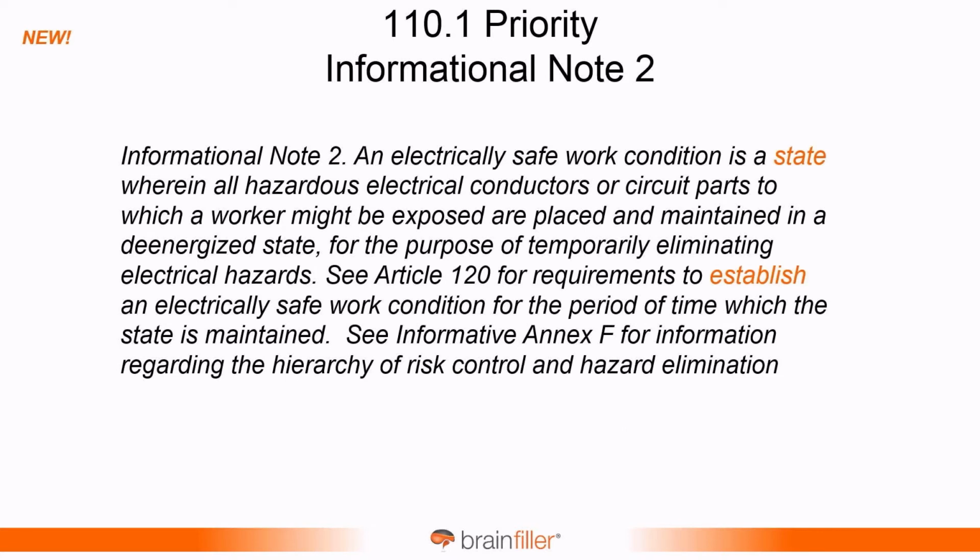There was also an informational note that's new. Informational note number 2, discussing that the electrically safe work condition, again, is a state. And it goes on to describe what that state is. But further down, it references Article 120 for the requirements to establish an electrically safe work condition. So really, we're looking at two different things. We're looking at the state of the electrically safe work condition, and then we're looking at what are the requirements to actually establish the electrically safe work condition.